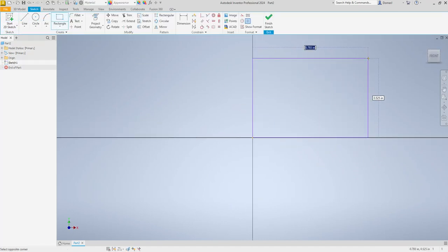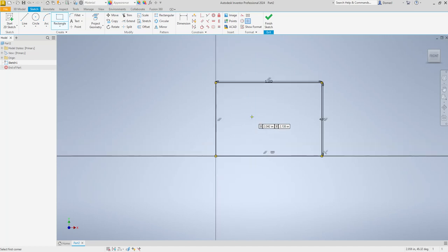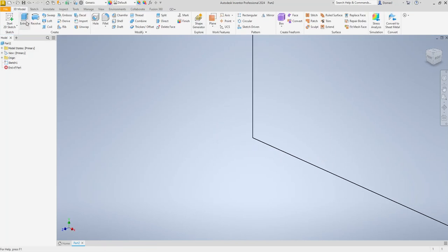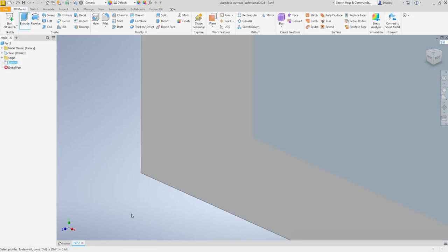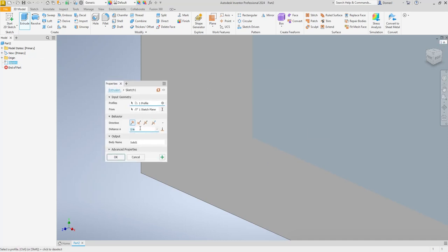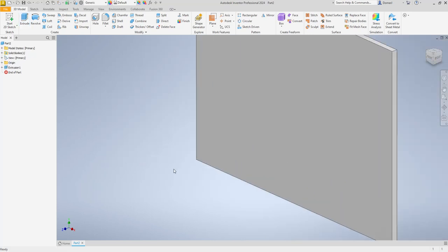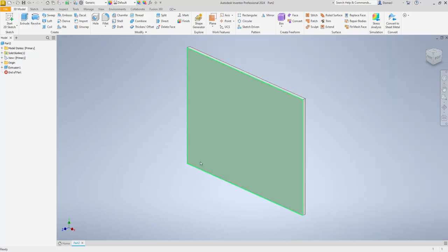And I'm going to create something that, and maybe you have a sketch already to go, which would be great. I'm going to go 6 by 4 inches to get started as a size. I don't necessarily have a sketch for mine per se, so I'm going to start with that size. I'm going to finish that and extrude that. Two windows here, my apologies. 1/8 of an inch to get started, and I kind of have a base plate ready to go.